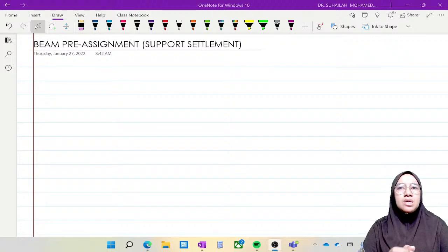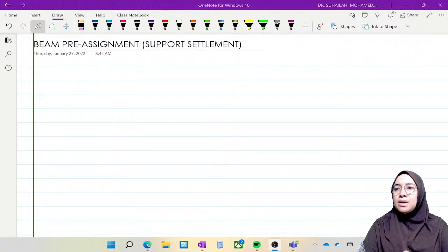Assalamualaikum warahmatullahi wabarakatuh. In this video, I would like to discuss one beam question. This is actually a pre-assignment question. I want to consider a beam with support settlement. Beam with support settlement means that we have to consider FEM due to external loading as well as FEM due to delta, which is the vertical displacement, since the beam is a horizontal member. Delta is given in the question and the external loading is also given in the question.